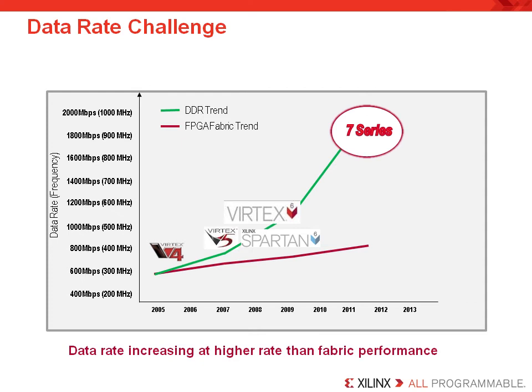Memory bandwidth is almost always the single most important performance bottleneck. It is important to realize that your overall system performance can often be very dependent on the available memory bandwidth. Thus, there is a continual push for higher and higher bandwidths from all 3 of the newest memory technologies, that is DDR3, QDR2+, and RL DRAM.